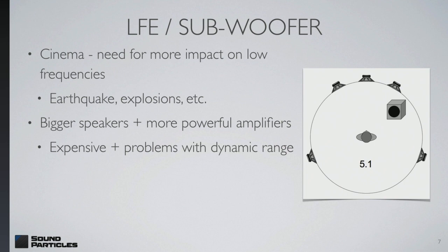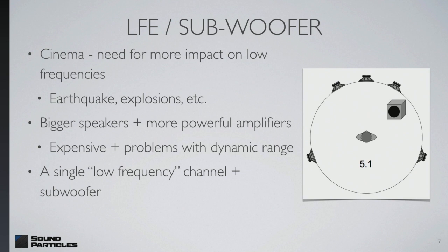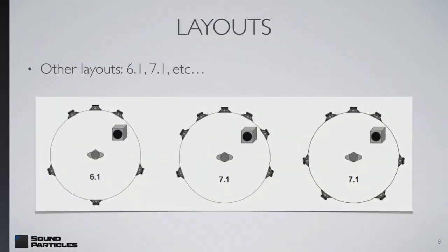So the decision was, okay, let's have one single low frequency channel with one subwoofer reproducing everything, and that's the reason why you have one additional channel and not simply bigger speakers and more powerful amplifiers. Also quite important, be careful, because when you're talking about LFE and subwoofer, they are two different concepts. LFE is the channel that brings this low frequency content, and the subwoofer is the speaker that reproduces the low frequency content.